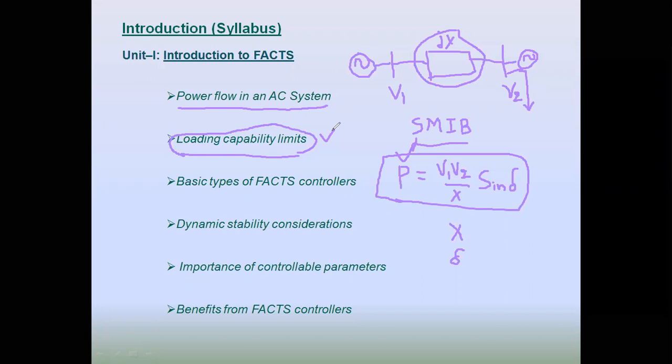Coming to the second one, that is important: every machine or every line, every wire generally will have a certain capacity, that is the insulating capacity, the dielectric capacity or strength. Generally that depends on the voltage. If voltage exceeds the rated voltage, then insulation damage will occur to that particular machine or wire or whatever it may be. So even the transmission lines also have a certain voltage limit. Even if it exceeds by 10%, that doesn't have any effect. It can bear that voltage.